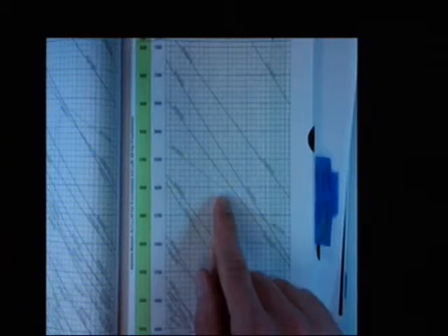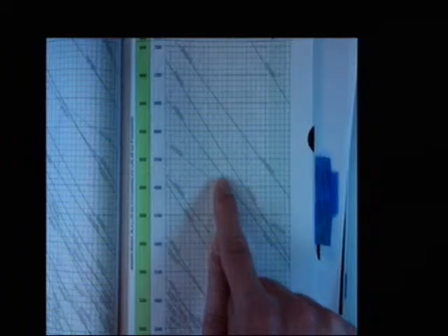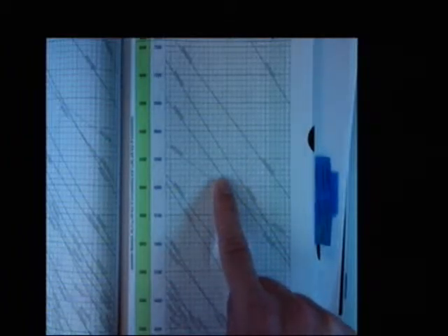It means there's a lighter member that provides that same capacity. So if you ever get to a point on the Snell chart, you keep going up until you hit a solid line, and that happens to be the lightest member that has that capacity for that section. Remember, the Snell charts are derived for a C sub B of what? 1. C sub B of 1.